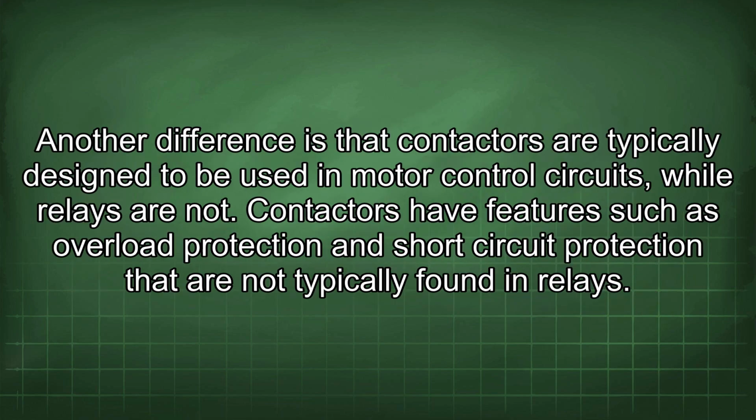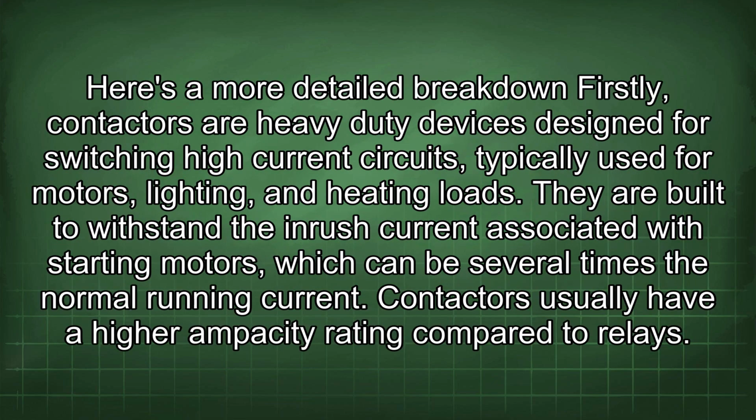Another difference is that contactors are typically designed to be used in motor control circuits, while relays are not. Contactors have features such as overload protection and short circuit protection that are not typically found in relays. Here's a more detailed breakdown.